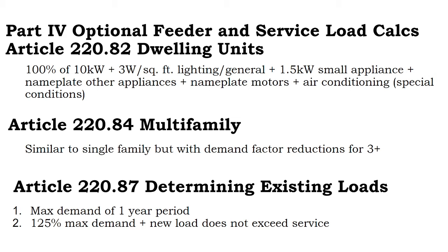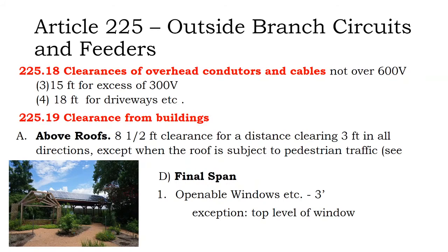If you just use generic load calculations and count up all the devices and all the circuits, the answer is yes. But if you have load data from either the existing home and you're doing an expansion and they want you to upgrade your service, or you're implementing load management devices, you can say, no, I can just keep my existing service. Sometimes expanded services cost more, sometimes they don't. Depends on the utility.